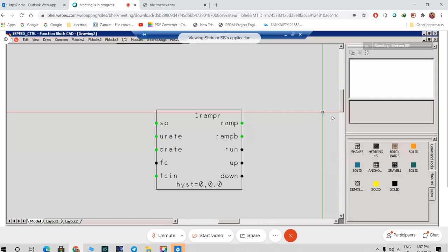And next is this simulation. Simulation will be, whenever you are trying to simulate a signal, that time it will show 128, that is simulation fault. And then significance of E1 to E5 error signals. E1 to E5 is not error signals. E1 to E6 are there in this MTR and all these drive blocks. Those are basically for any emergency fail-safe condition you want your drive to go to. So those conditions you can configure in this E1 to E5.